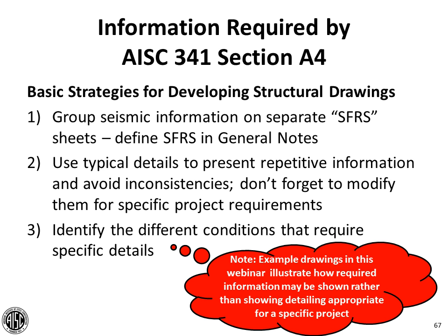One of the things that many engineers have found is that grouping the seismic-specific information on separate seismic force resisting system sheets, or SFRS sheets, really can simplify things by a large degree, because then it's clear to everyone that this is where the special detailing requirements, things that relate to pretensioned high-strength bolts or some of the other requirements related to welding, apply.